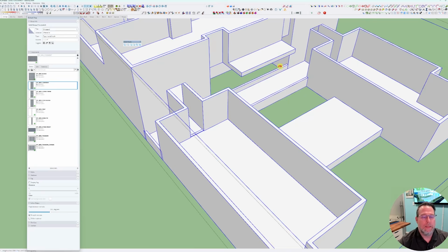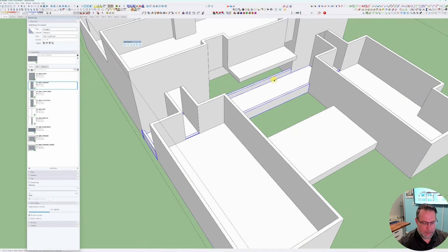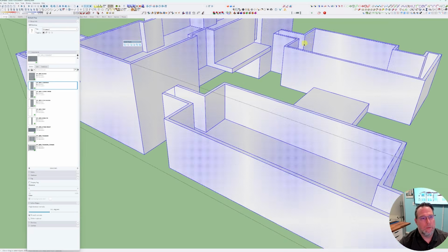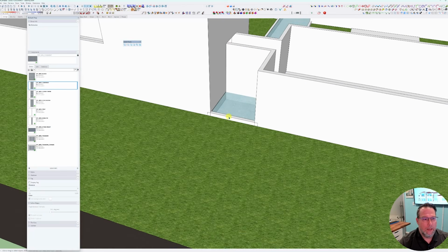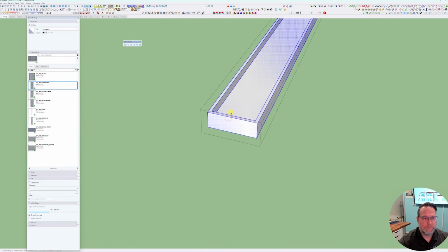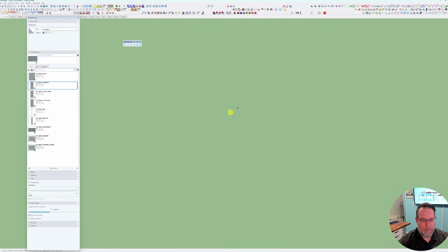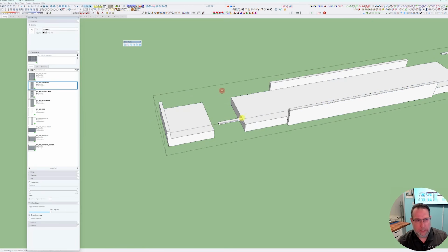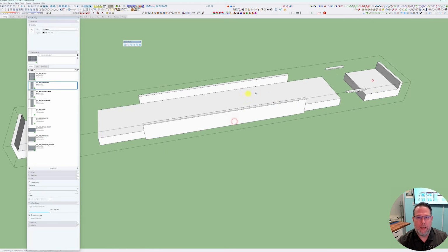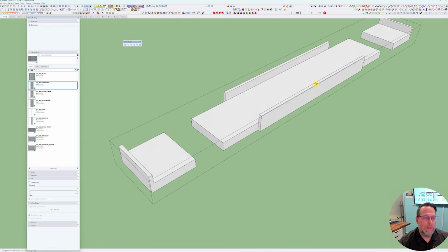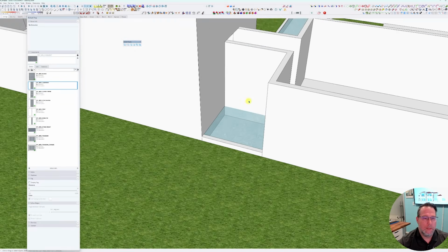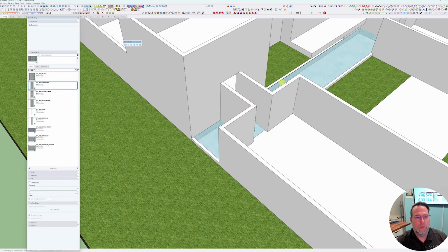So I'm going to paste the walls back in. I'm going to grab my pool. I'm going to cut the pool out of my house and then explode this. And now if I come into the pool, I'm going to delete my old pool and paste this one back in and explode. And we just got to get rid of these little nubs that got left behind. But this pool is now perfectly conformed to the house, and that's what's so great about solid tools.